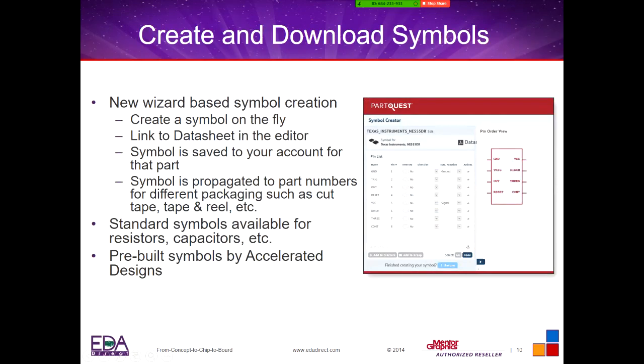What's also nice, and this is new, Mentor's always had a component and a cell generator inside the tool, but now instead of leaving the PartQuest tool, you can actually go in and create your own schematic symbols or your own footprints. So we've actually put the symbol creators inside of PartQuest, so you don't have to be back and forth in and out of PADS creating those symbols. You can be in PartQuest, create the symbols, and then push them right into your library.